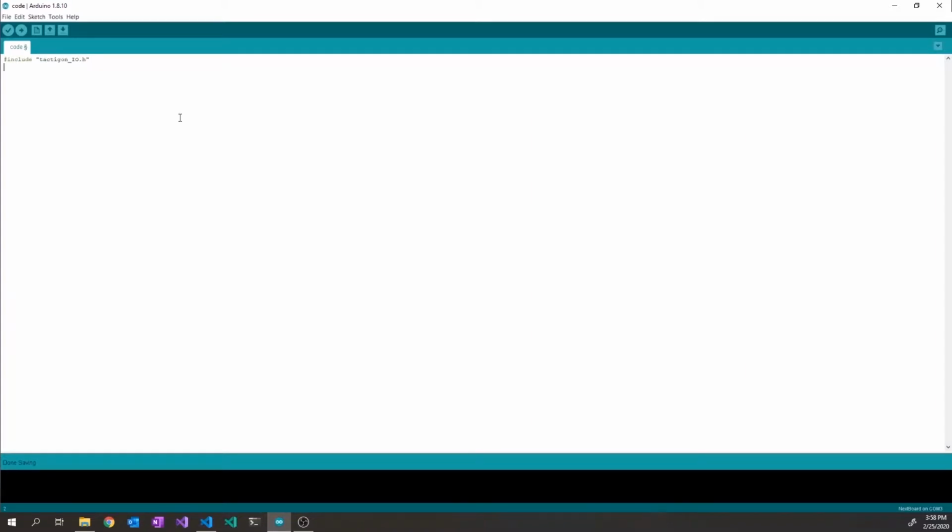Now we're going to include the Tactigon I/O and Tactigon LED libraries. Those libraries contain all the necessary functions that we're going to need. We will be declaring the RLED, GLED and BLED handlers, and also the GPP1 through GPP4 handlers. The first are used to manage the onboard LEDs, and the second are used to initialize GPIO ports. Then some variables are declared to keep track of the button state and the LED color cycle.